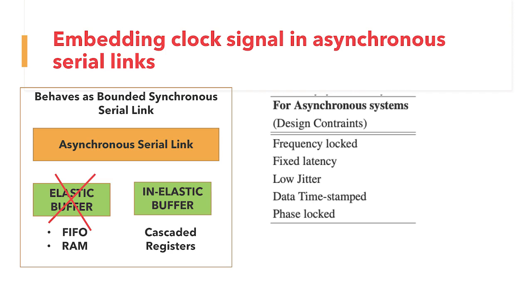And then we have to timestamp the data point. And the last one, but not least, is the phase locked point: how to phase lock this design. For example, if there is a power reset or firmware upgrade or just a reset assertion, you have to make sure the signals are locked each time you do any of these cycles. So that's why these 5 constraints are very stringent in high energy physics.